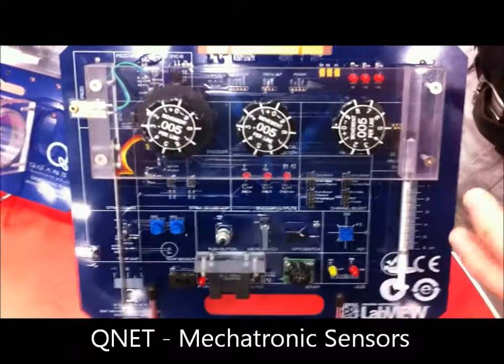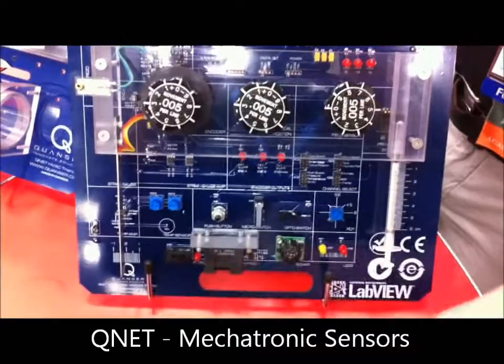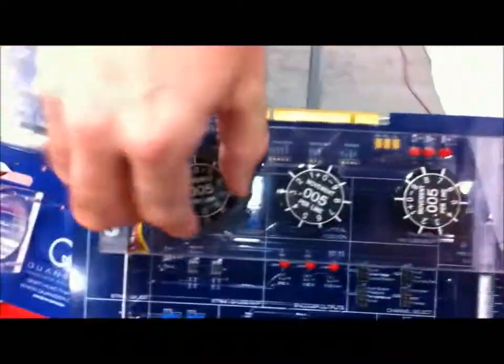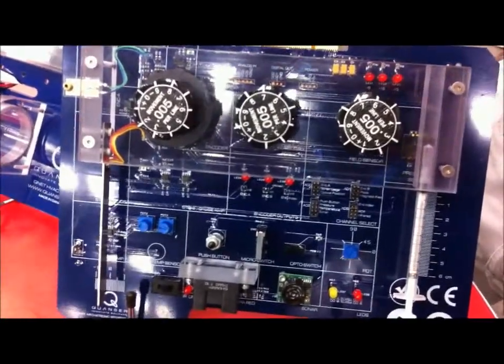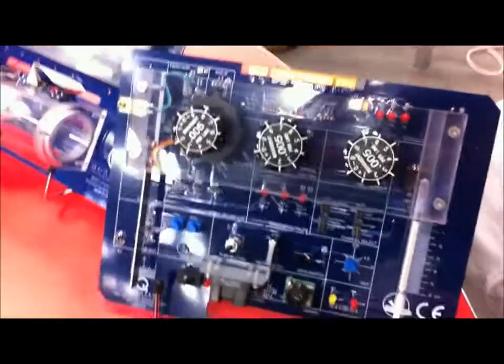So we have a myriad of different sensors from sonar to optical distance to switches, an optical encoder up here, a couple of other distance sensors. And the main purpose of this is to teach students how to interpret and interface to these different sensors. For example, on these switches, when you close them, you see what they call bouncing.